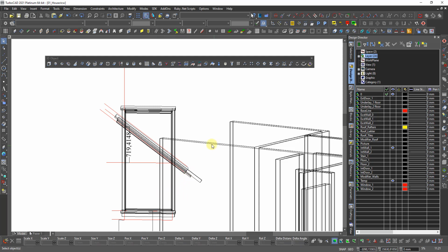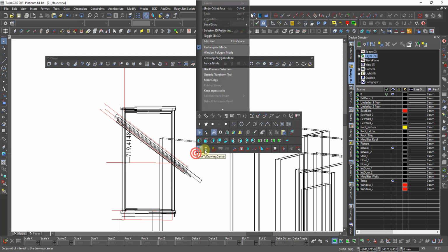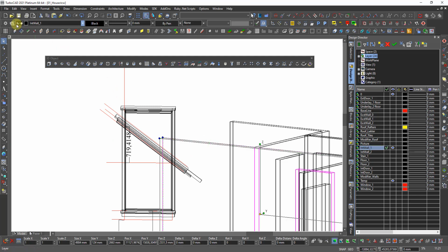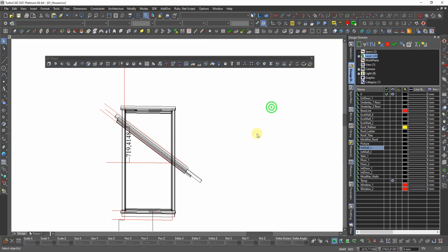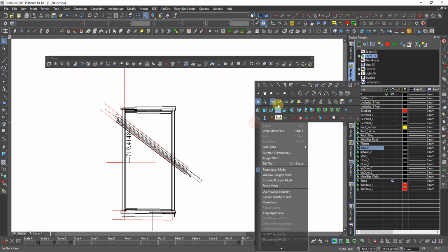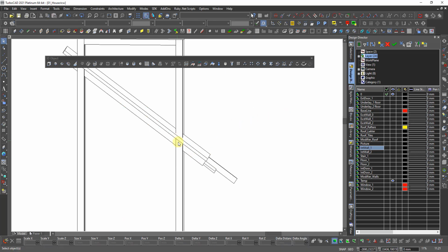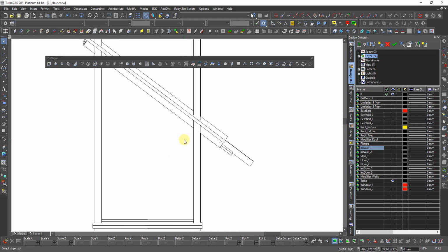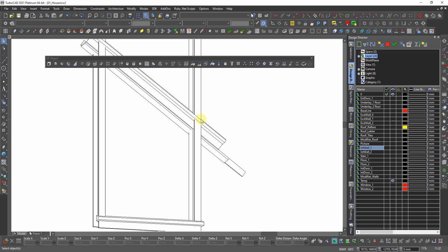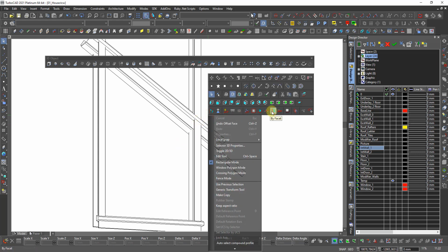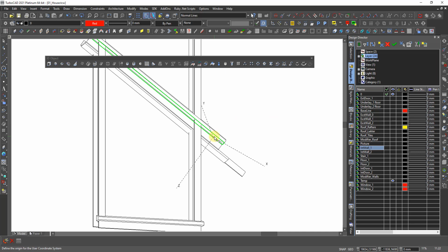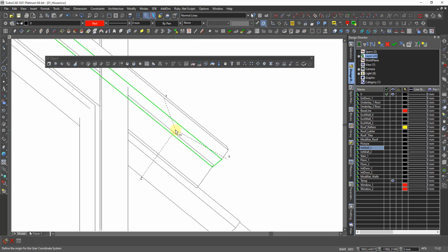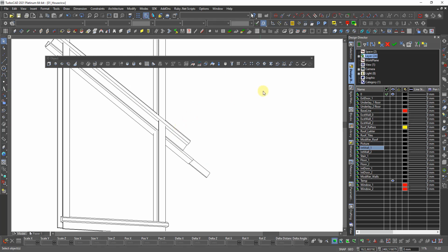Then we can continue. Need to pick up some coffee. Now we should slice and dice a lot. So first I turn off this wall, so I don't slice them by accident. Slice is a powerful tool. So I go to hidden line, and it's the same principle like the other. So I want to have my work plane under here. Then I say work plane by face on this top waterboard. I say there, and I slice.